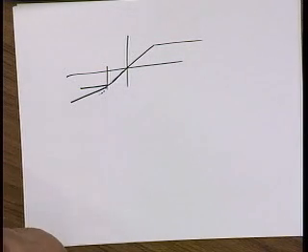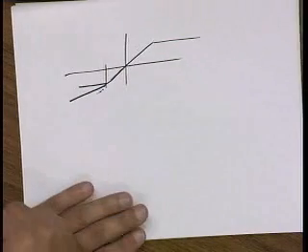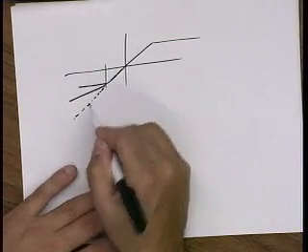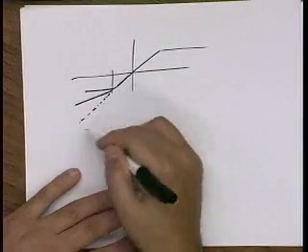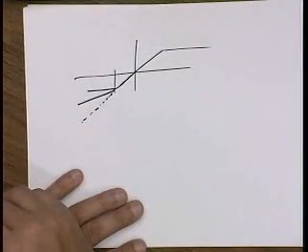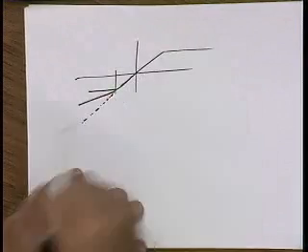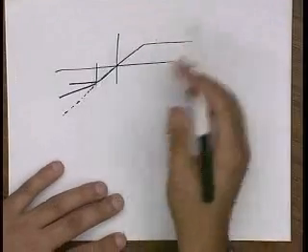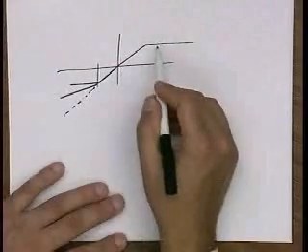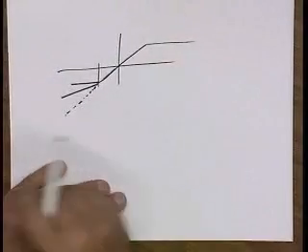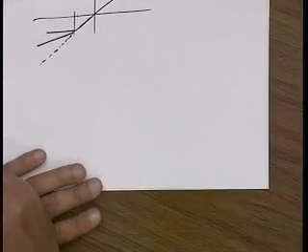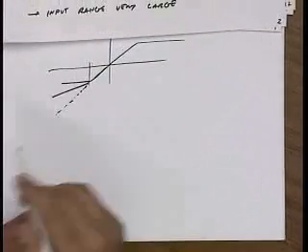And in fact, I can fix that problem by somehow increasing the current in the PMOS stage under this condition so that I get back roughly the same gm. And then vice versa, right? If I go too high, the PMOS turns off and I can actually dynamically increase current on the NMOS side. So let me show you how we would do that without making it too messy.